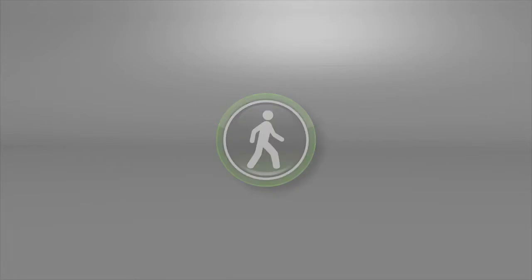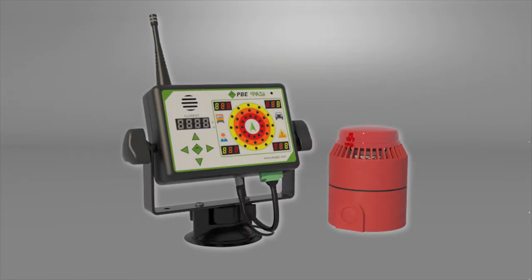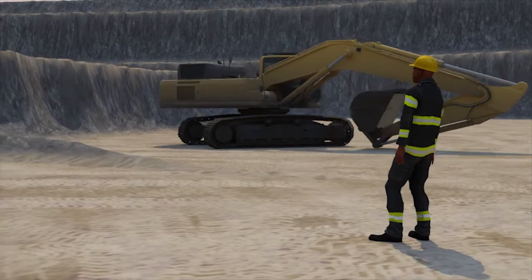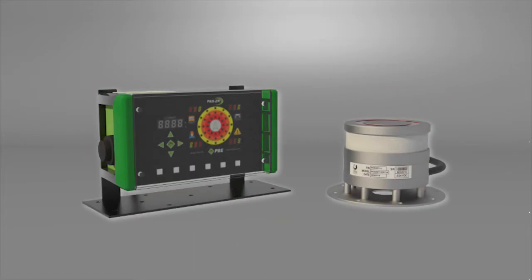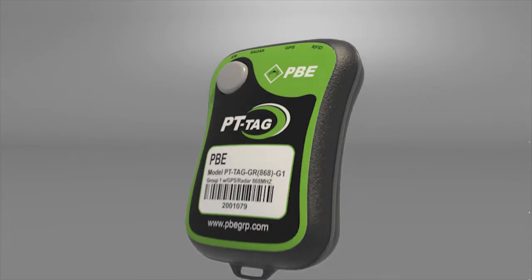Pedestrian detection. When a vehicle is in a pedestrian's proximity, the pedestrian's PT tag will flash and sound an alarm. The vehicle's PASS unit will also flash and sound an alarm. When the vehicle passes out of the pedestrian's proximity, the lights and alarms of the PT tag and PASS unit will stop. When a pedestrian is in a vehicle's proximity, the pedestrian's PT tag will flash and sound an alarm. The vehicle's PASS unit will also flash and sound an alarm. Once the danger has been acknowledged by the pedestrian, the PT tag button can be pressed to stop the alarms and flashing lights.